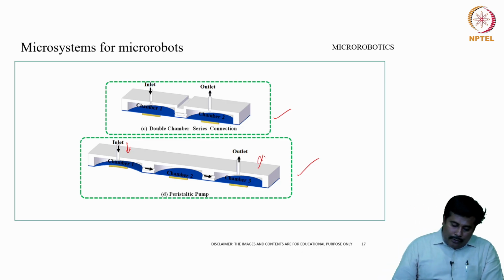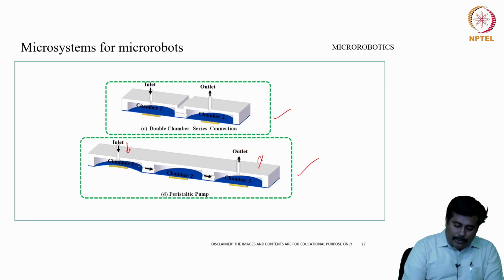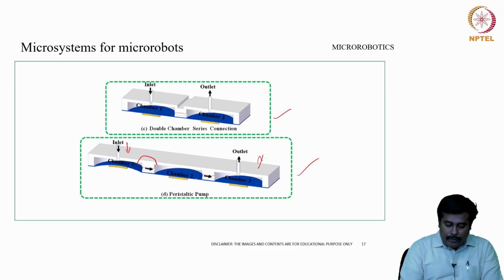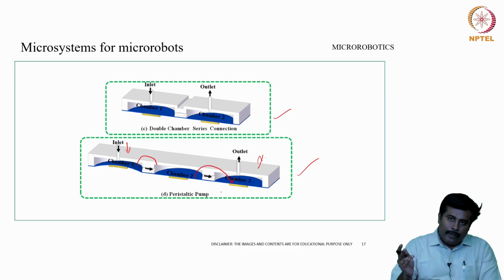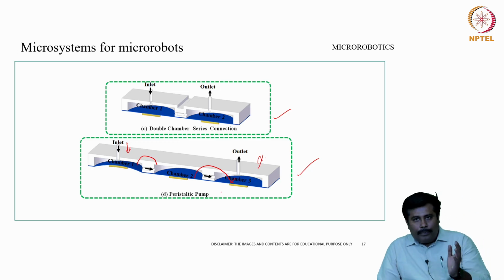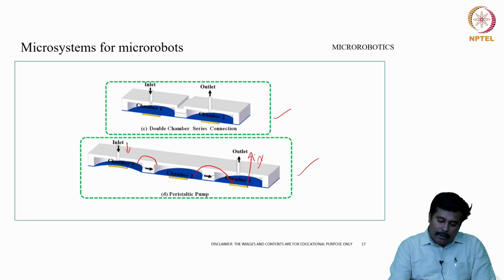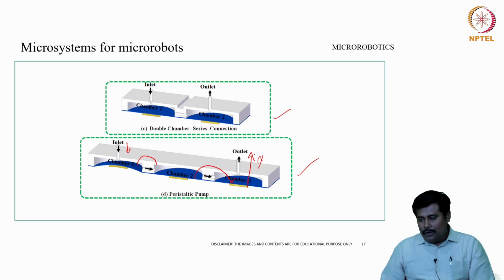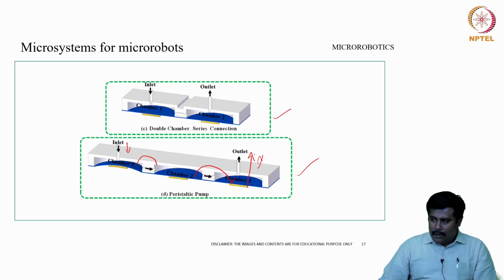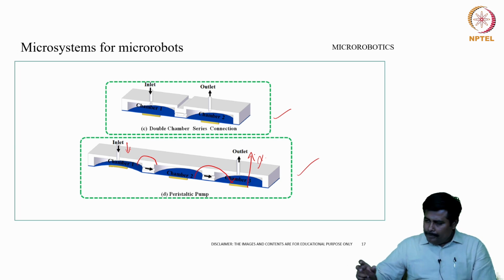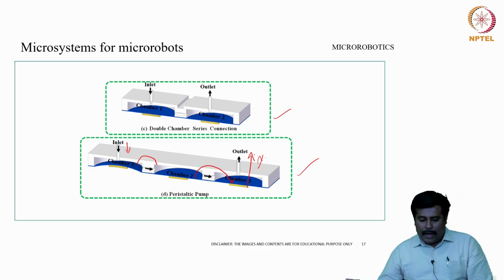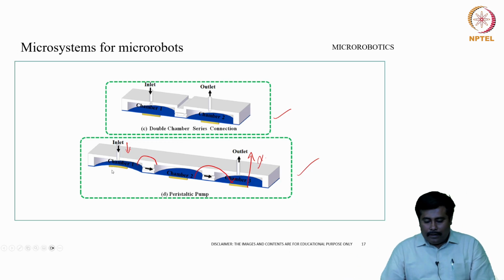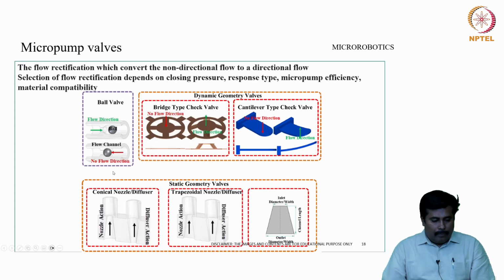Due to the pressure difference between chamber 1 and chamber 2, the liquid available in chamber 2 will try to move to chamber 3, unless a pressurized fluid is made to move to chamber 2, and appropriately there will be a flow through this outlet. So, in this case also, wherever we need mixing of a fluid or a different time delay, such peristaltic pumps can be deployed.